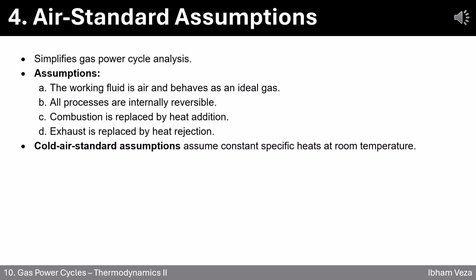Second, all processes are considered perfectly reversible. No friction, no losses, making calculations simpler. We also replace combustion with a simple heat addition process and exhaust with heat rejection. This means we don't need to model fuel burning or exhaust gases, just focus on heat transfers.